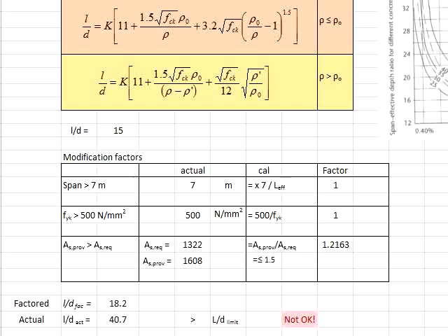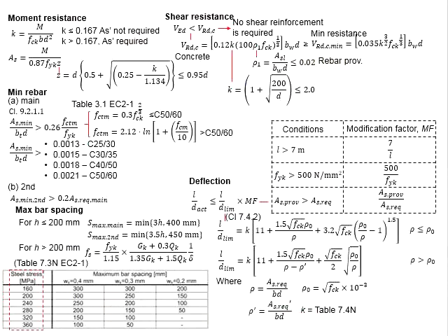There is another way for you to increase the chances of passing, where you might need to increase the grade of the concrete. But I believe the contribution will not be that significant. The most effective way to pass the deflections would be by increasing the thickness of the staircase. With that, this concludes the entire chapter on the design of the staircase.